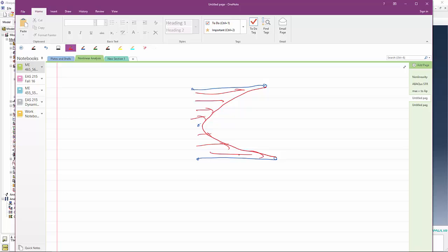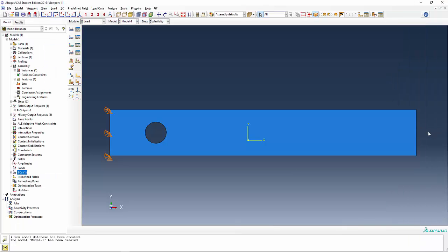As you're doing that, you have to be careful about how you implement the coordinate system. So I want to define a coordinate system so I can attach the function that I'm going to define to that coordinate system. So where do I define a coordinate system? Let's go ahead and create a datum coordinate system with 3 points. The icon that you see that I've highlighted, it's going to be the rectangular coordinate system. I'm going to call that shear load coordinate system.